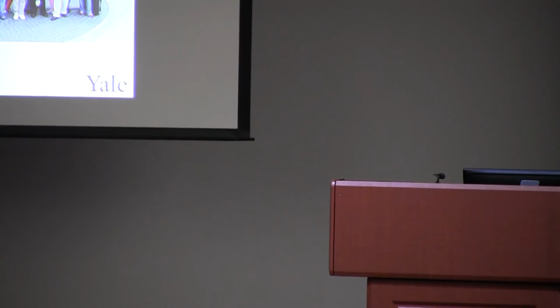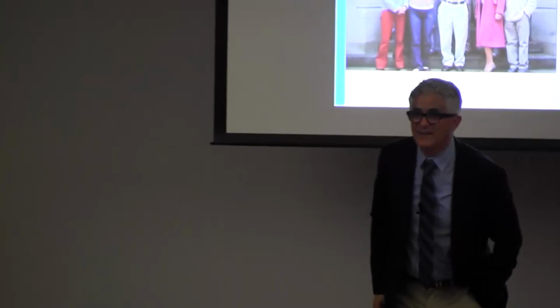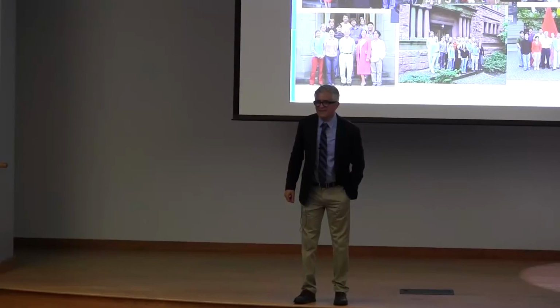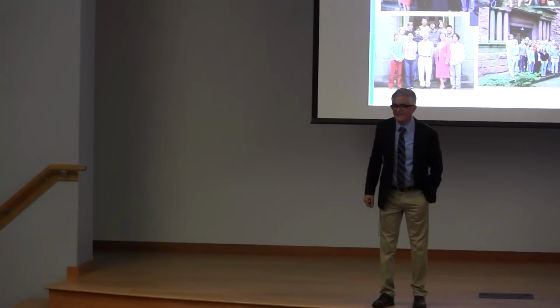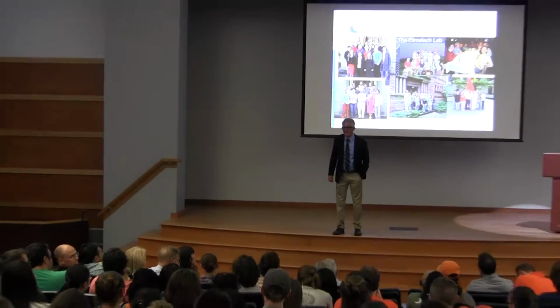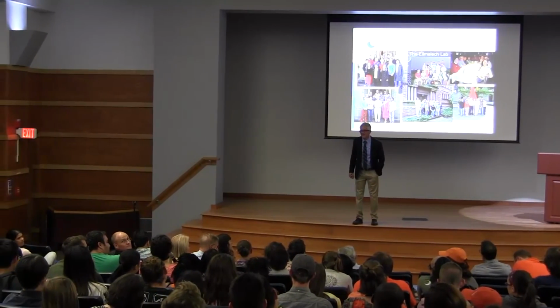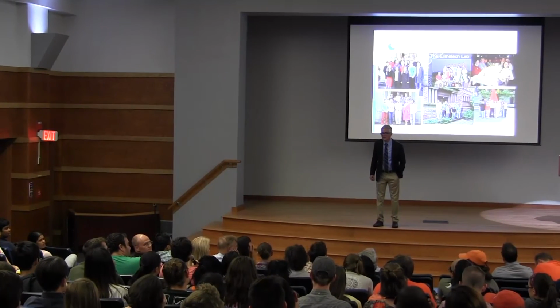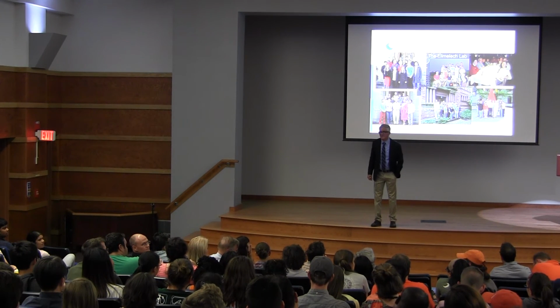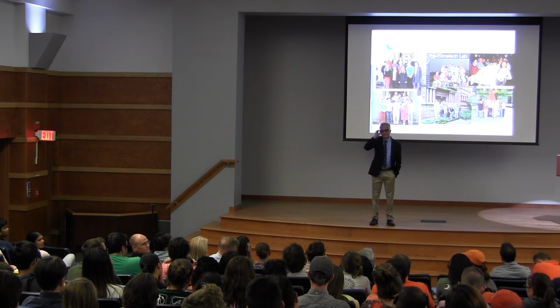Hi. Thank you for your talk. You talked about the trade-off between selectivity and permeability, and about how we can move towards more selectivity to increase the efficiencies of RO. I was wondering, given the emergence of new contaminants, like boron and others, will there be commercial viability for less permeable but more selective membranes that have less high flux?